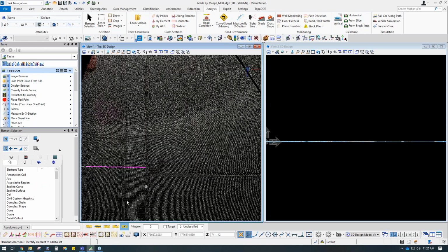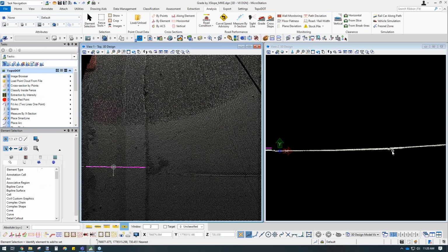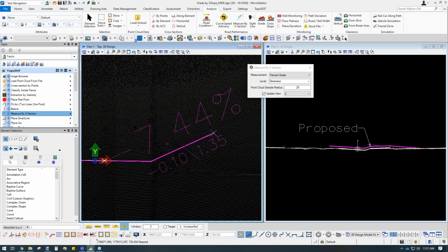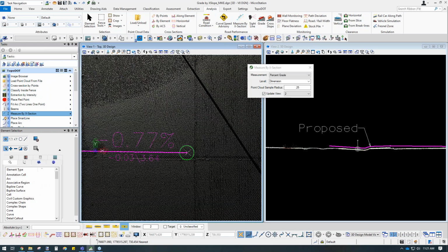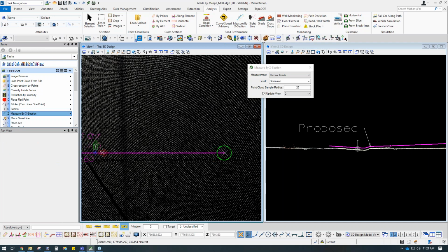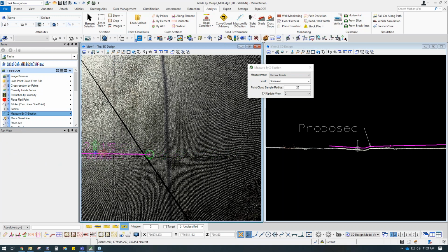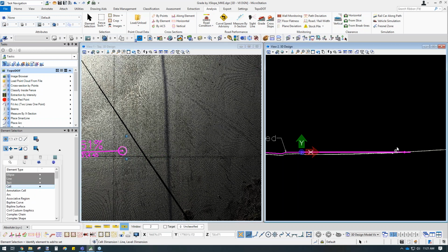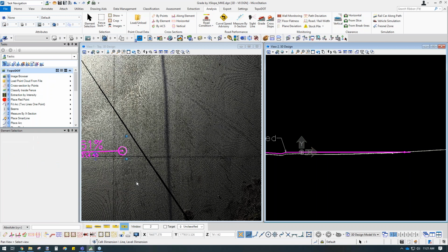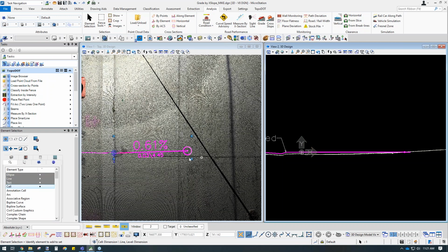Now, one more example before I move on. Let's say you get proposed work or something like that, and they just want to know where my tieback points are, or where I can tie into the existing ramp at 2%. They say, okay, we're going to be raising the curb. Here's the proposed. You activate the tool, click in to that location, and then you can just use the control option to determine how far back do I need to go in order to hit that 2%. I know it's hard to see for you guys, but this is the idea on how you would use this tool. That way you know your tieback points way back here. So you could probably work with this segment here and just rip up in between.